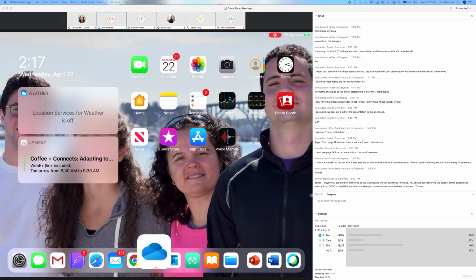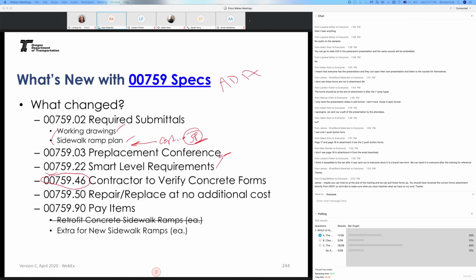At the end of the day, the way I usually talk about this section, I would say it's a story or a communication plan or expectation, starting to tell the contractor, hey, here's what I expect from you. You submit this, check the plans. Go to the field, verify. So give me your plan, contractor, how you're going to build it, if it meets the plan or not. Give it to me 21 days before. Don't give it to me the day before the pour.